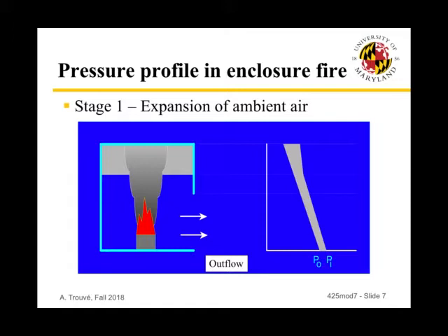And that means that there will be a natural tendency for the heat release process to drive the pressure to high levels. And the pressure inside the fire room will be larger than the pressure outside. So if PI is greater than PO, we can expect outflow through the open vent because the flow will go from high pressure regions towards low pressure regions as predicted by Bernoulli.